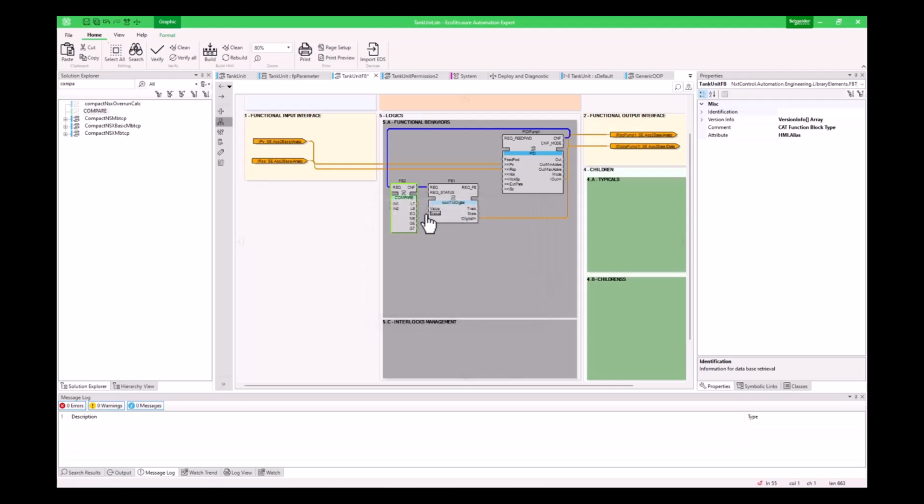The pump also needs an automatic mode enable signal. I'll generate this signal automatically when the PID output is above 5%.